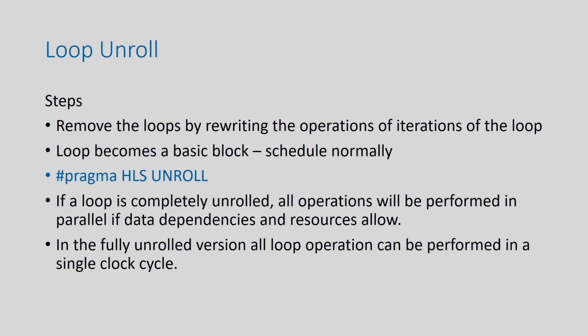So, you can understand here that in practice, if there is no dependency between two iterations, iteration I and iteration I plus 1 operations are in parallel, right. So, if I assume that one iteration takes one cycle, I can execute the complete loop body in a single cycle, right. So, earlier it was n cycles, if I assume each iteration takes one cycle, but here it is one cycle. So, it is a complete extreme end, but there you need only one unit of resource, here you need n units of resource, because all n iterations are running in parallel. Okay. So, this is the other extreme.